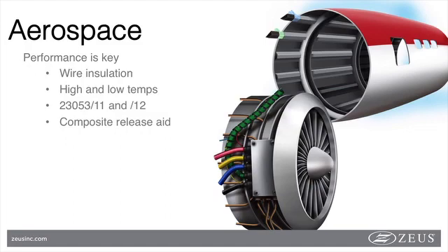Don't just think wiring though. Composite engineers often use FEP film as a release aid as it can withstand high autoclave temperatures and has excellent lubricity. Designers making parts that are round, trapezoid, hexagonal, and more should consider thin FEP heat shrink, which can save time and money without sacrificing the properties of FEP that are beneficial in the application.